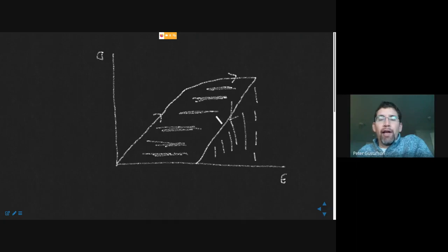So that's energy going into the material, largely becoming heat, and there would be some elastic energy still available. But you have to be really careful when you're talking about strain energy in the context of materials that have gone into the plastic zone because you don't get all the energy back.